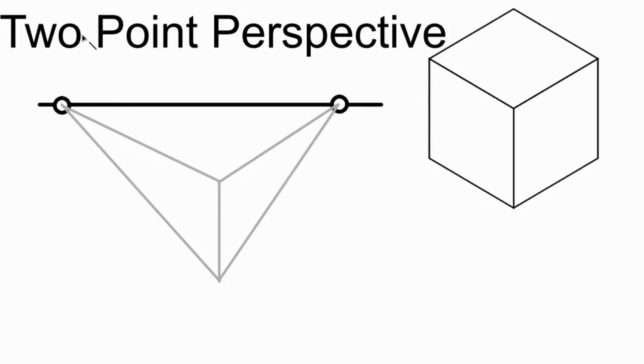So I have this. I need to drop in my vertical lines, and I'm going to do this as a visible line because that's what it is. It's a visible line. I'll drop that in there, and I'm going to darken in my front line as well. So I have the 2 lines of my views done. I just need to connect them with a line, which I can do here, and that will complete the front view for my part. Again, it's going to look a little funky. It may not look perfect. That's okay. Now we need to get our right view drawn in there, and we need to figure out how to do the top. So the front view is done.